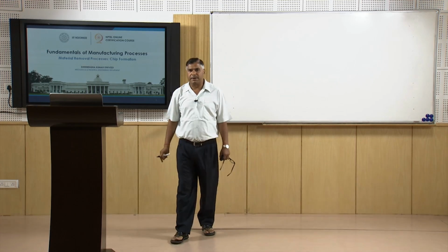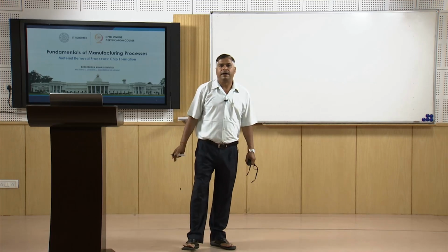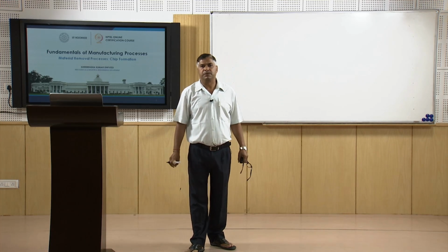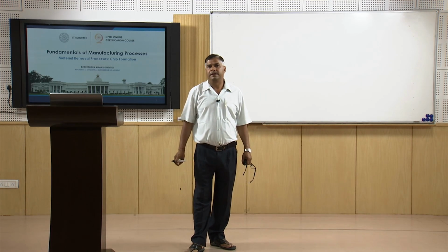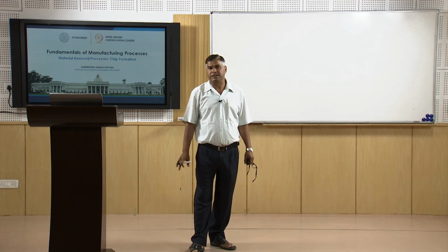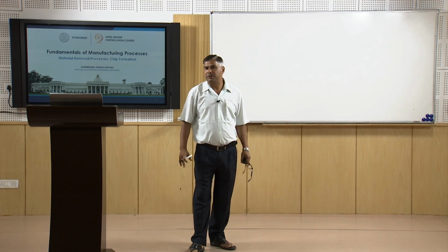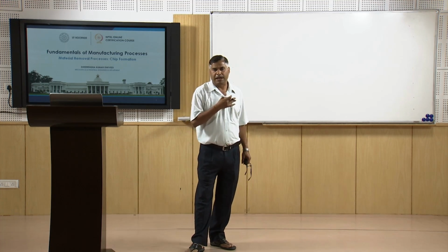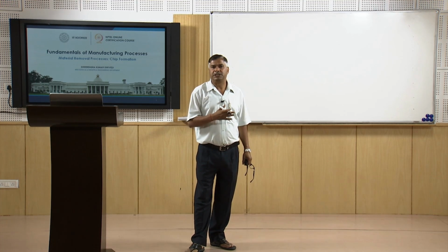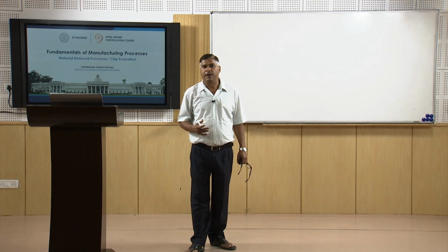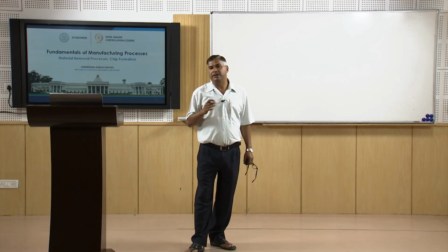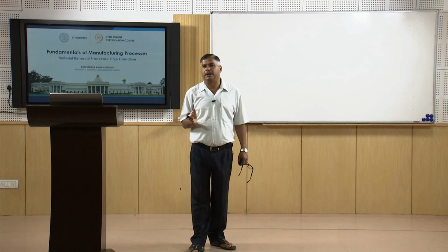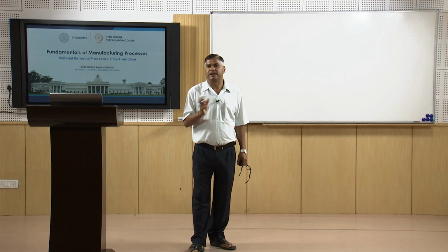Now I will summarize this presentation. In this presentation I have talked about the machine tools and the actual chip formation approach. We have seen that the actual chip formation approach is different from the ideal chip formation, because here the shearing takes place over a certain zone, and the shearing also takes place between the tool rake face and the chip.